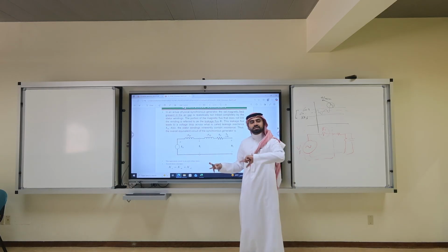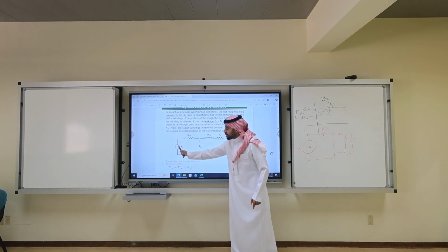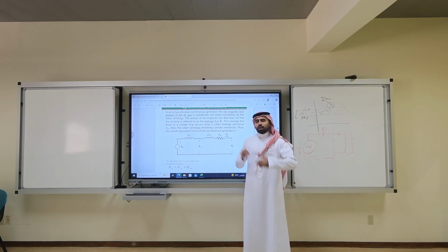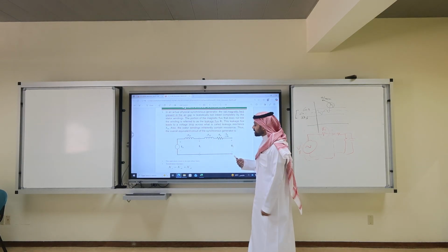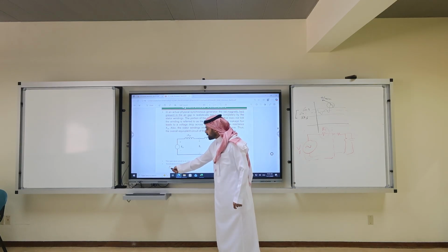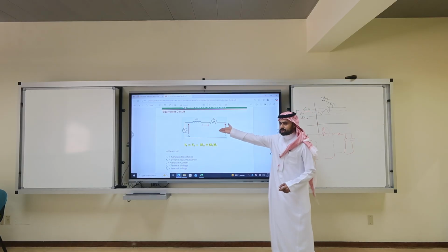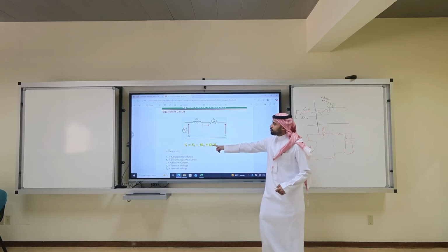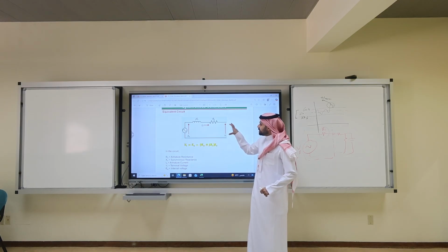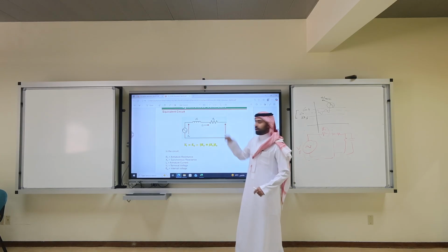Is this a single phase circuit or a three phase circuit? Single phase. So is this phase voltage or line to line? Phase voltage. Now to simplify the analysis, sometimes they combine XAR and XAL into something we call XS, which is the synchronous reactance, which is this circuit. If you do voltage rise, voltage drop, you should get this equation: Vt is EA minus IA jXS minus IA RA.